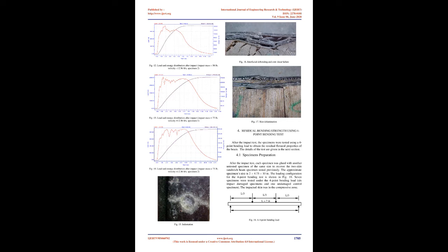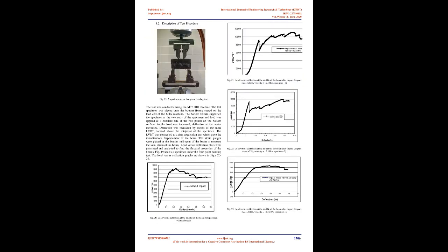In this study, the impact velocity was fixed at 12.56 feet/s and 3 hammer weights were used, 25 pounds, 50 pounds, and 75 pounds. The test temperature was about 60 °F. The load time and energy time curves for each specimen are shown in Figs. 9 to 14. 3.3 Impact Test Results and Discussions.